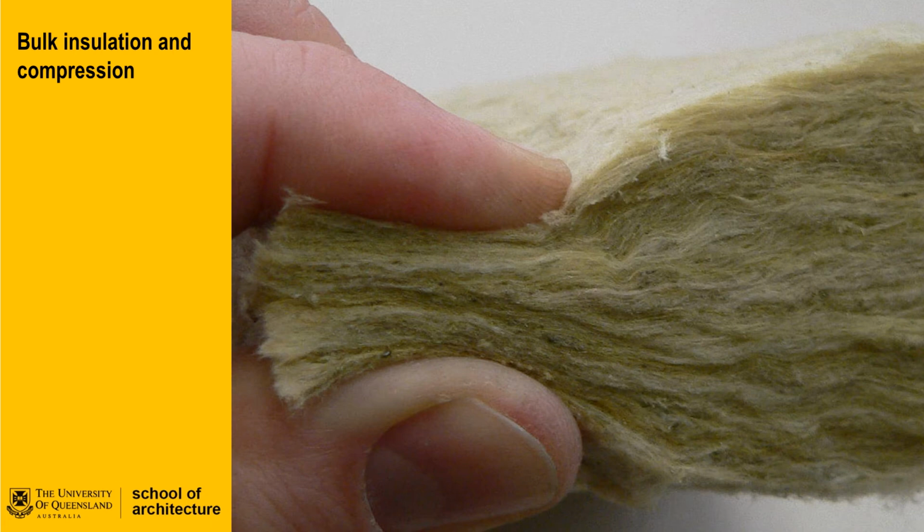As designers, we must ensure that in instances such as the filling of material in cavities, around surfaces and in roof spaces, it's not compromised by compressed insulation. Designers need to be aware that the thickness of insulation needs to match the clearances and the sizes of structural elements.